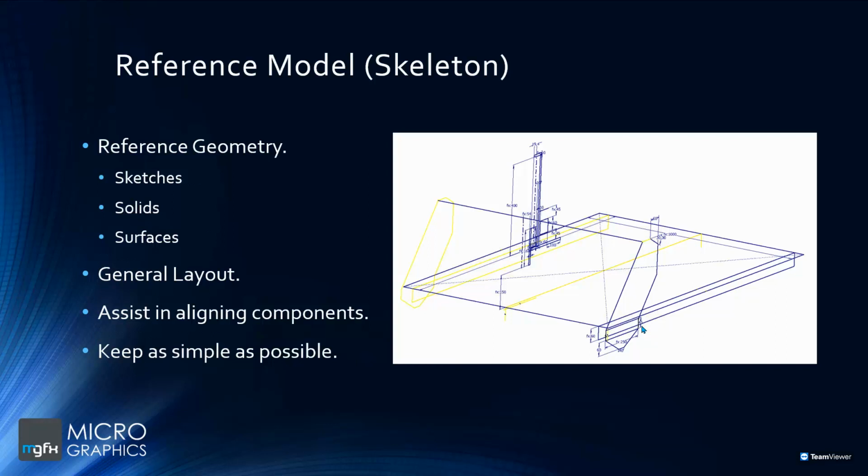And without a lot of effort, we're able to troubleshoot potential issues right up front before we've invested too much time into the 3D design. At this stage, you want to keep things as simple as possible so that you're able to get a quick layout done, troubleshoot any issues, maybe rethink your approach, and then start adding more complexity to the model. And if you find that something starts to get too complex, you could always derive out information from this reference component into another one.